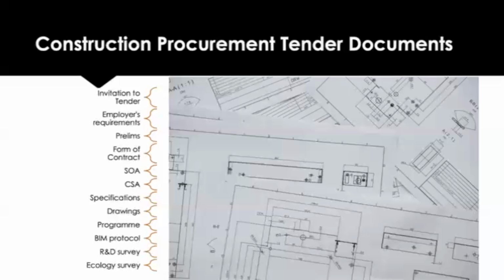And then under the specifications, you might see drawings and copies of things like the feasibility study or the options appraisal. There could be concept drawings that have been sketched. Some designers will differentiate between a conceptual design and a schematic design. But the concept is the initial design idea, where the scheme develops from, whereas when we get into the schematic design, it's more functional and practical. So those detailed drawings can be technical, shop drawings, installation drawings, but they need to form part of the contract and part of the tender.